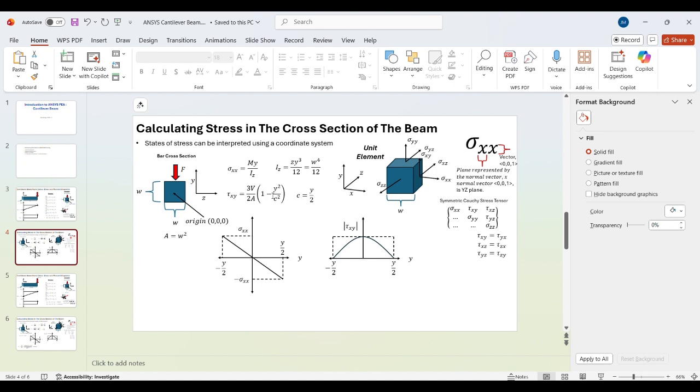So as y goes from the outer edge towards the center, the stress will peak and then it'll go back to 0 on the opposite outer edge. And I've plotted them here. So these are the results that we should see on our linear or our path geometry and our linearized stress.